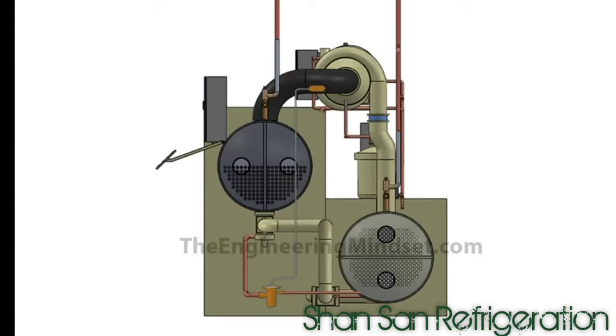So just to give you a side view of how it's all connected. We've got the pilot valve located down here with the connection going to the condenser, and that flowing through into the base of the main expansion valve. We've also got the capillary tube which rides up here into the thermal bulb which is attached to the suction line just before the compressor. And then the main refrigerant flow will pass through here, through this pipe, into the main valve. This expansion valve decides if it's allowed to pass or not, and if it is, then the refrigerant will flow into the evaporator.